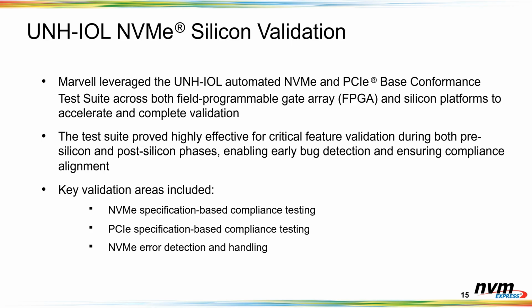The test suite proves highly effective for critical feature validation during pre-silicon and post-silicon phases, enabling us to do early bug detection and ensuring compliance alignment. So the key validation areas we have here are NVMe spec-based compliance testing, PCIe spec-based compliance testing, and the last one is NVMe error detection and handling.